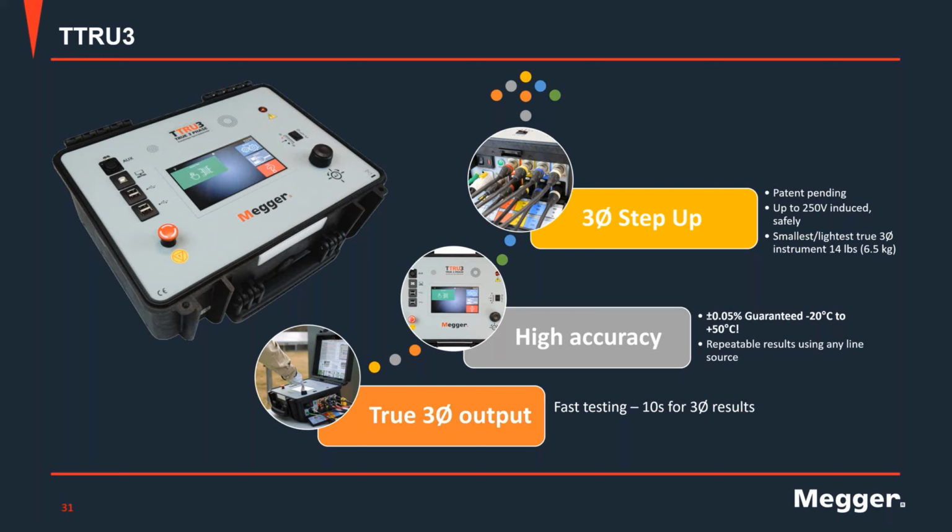And finally, the third major feature is three-phase step-up. It's a patent-pending algorithm that will actually perform a step-up test, assuring that the instrument will never have to deal with voltages more than 250 volts. So the unit will check the ratio of the transformer and then adjust the output. So again, you will never deal with more than 250 volts. It's really important to highlight this. When you want to perform a three-phase step-up measurement, make sure that you have a unit that is capable of performing the test that way.